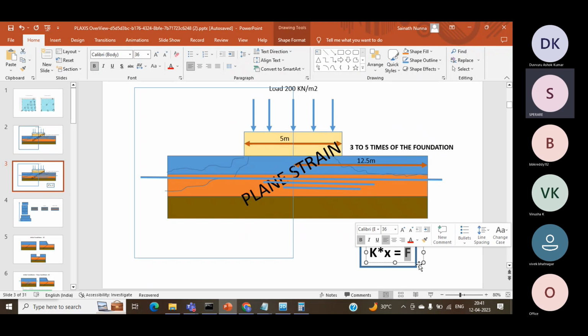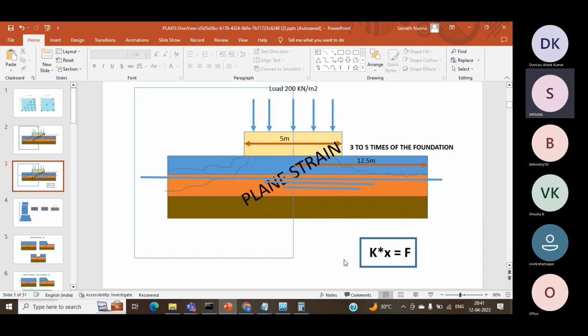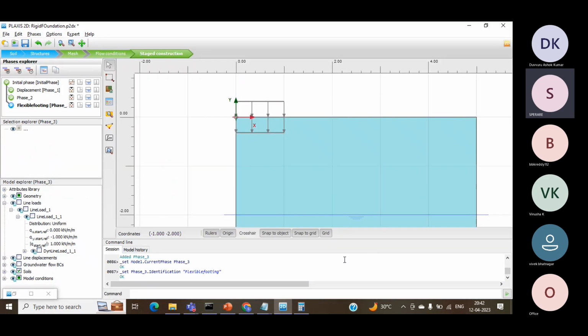While calculating matrices, division is a very difficult task, but multiplication in matrices is a straightforward calculation. So always, if you don't know the load, just keep it as kilonewtons as the load and try to achieve the displacement, and find for which displacement you achieve that particular 79 kilonewtons. In that way, you try to work this out. Then only your convergence equations will be quite normal. It would be very easy to achieve.